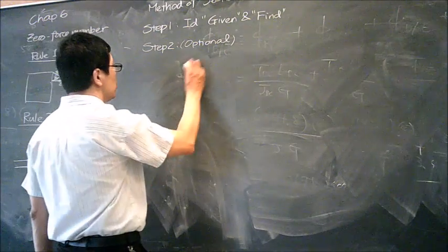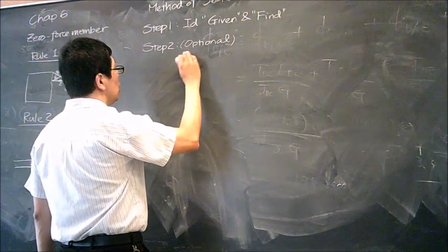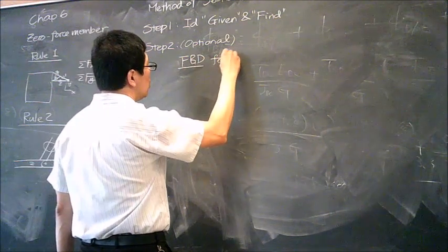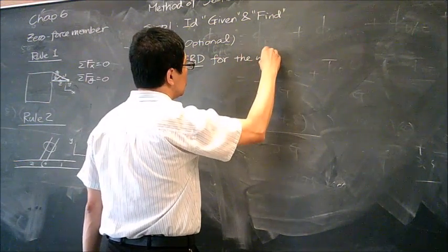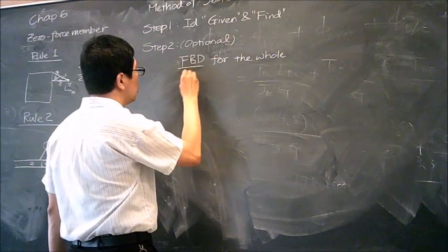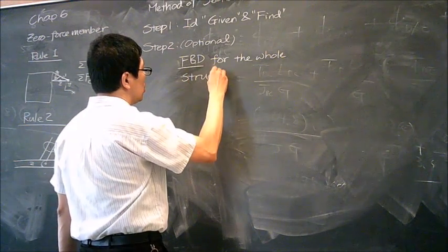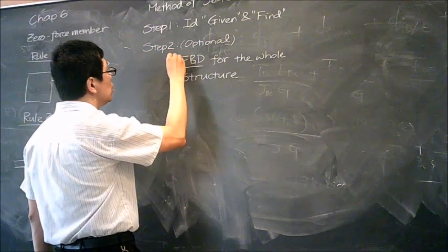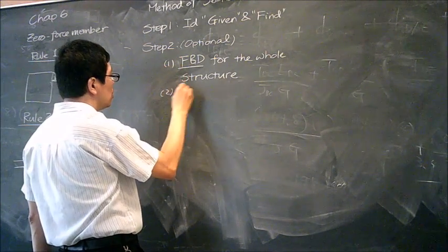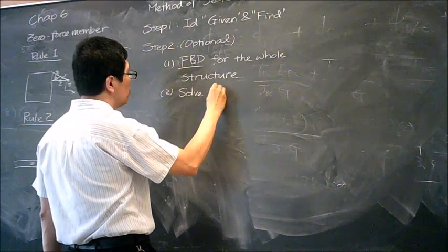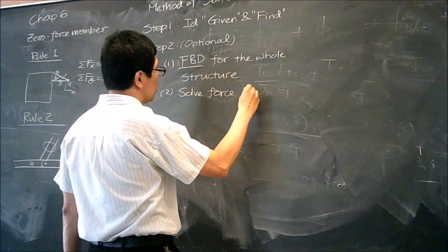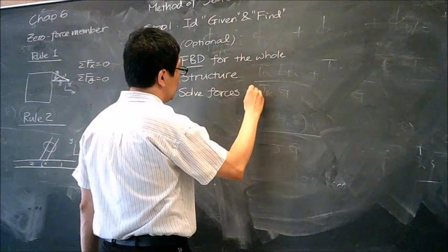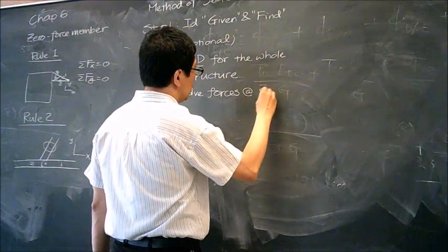So in that case, you need to have a free body diagram of the whole structure. Then solve for the forces at the supports.